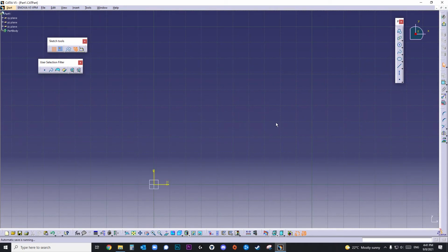And finally, the final command, the centered parallelogram. In order to show you this command, I will first draw two intersecting lines, because now when I select the centered parallelogram command, it will ask me to select the first line and then a second line.